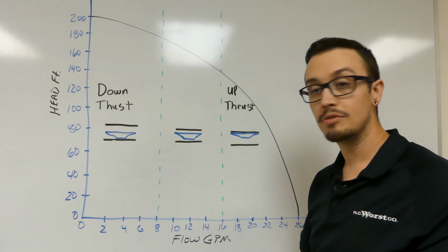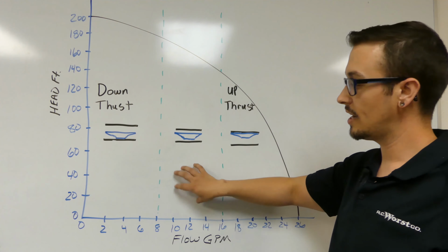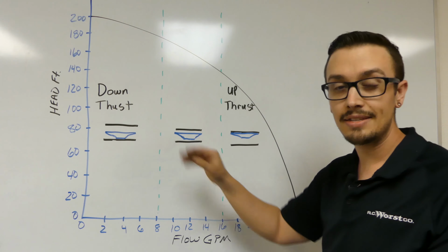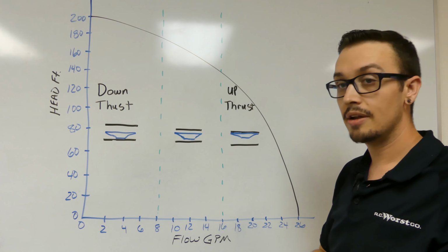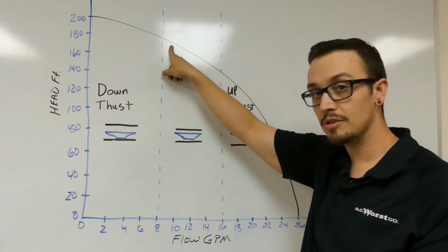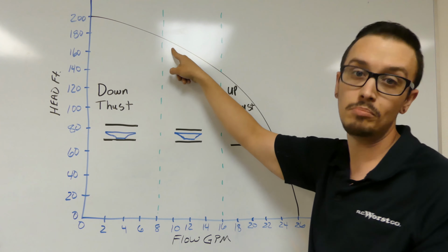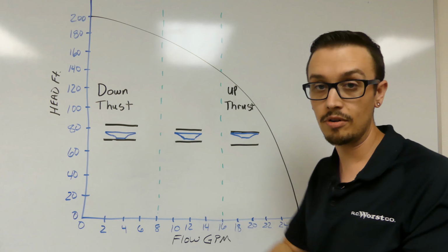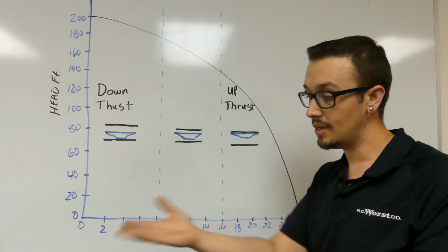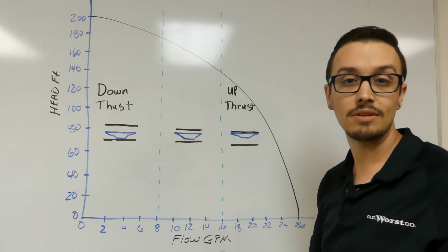Having that pressure tank means that when you size your system, you're always going to be operating in the middle as it's filling that tank up. So when the pump kicks on, it's probably going to be somewhere out here, and as the pressure increases in the system, it's going to be up here, the tank's full, the pump shuts off, and the cycle starts all over again. So that's an ideal situation. Let's jump into what I've got set up over here and take a look at it.